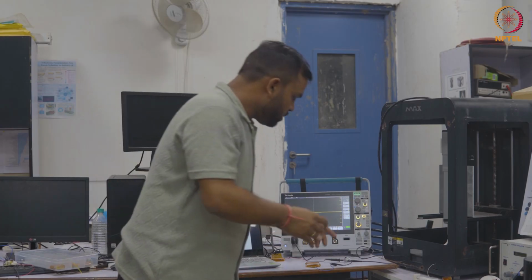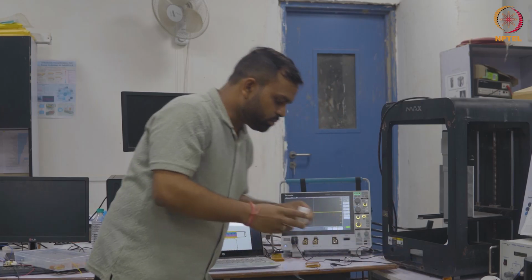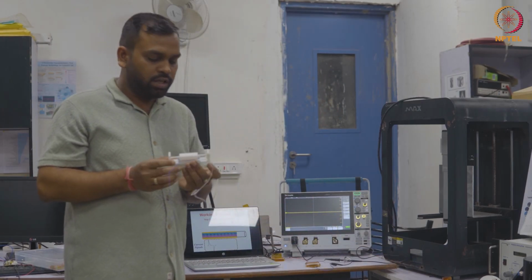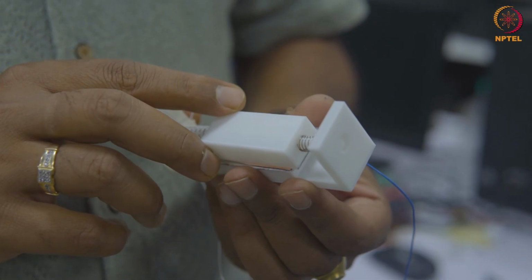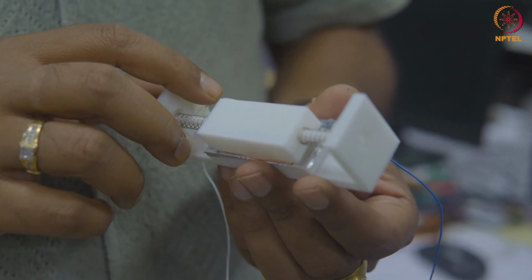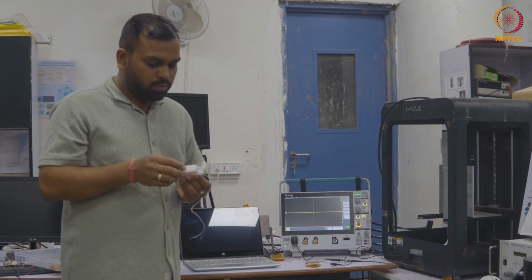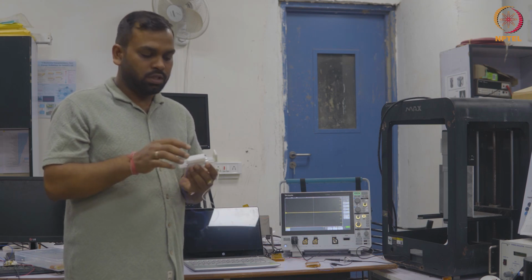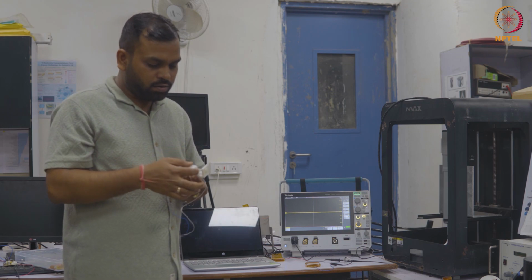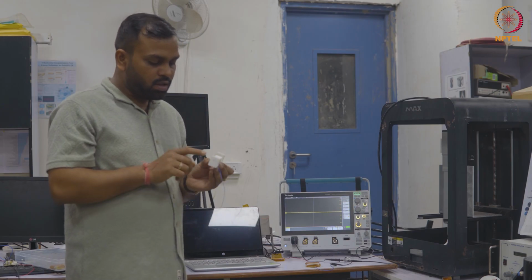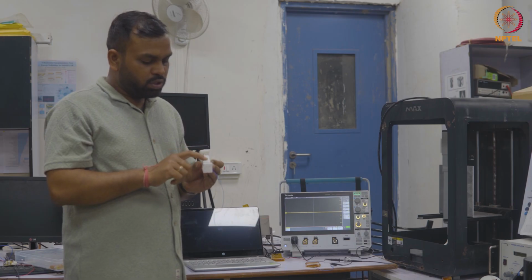So now, apart from contact and separation mode, we have a sliding TNG also. Both surfaces will rub against each other. Again, in this also we have FEP as well as aluminum, and both surfaces will rub against each other. We have applied some spring, so that with continuous vibration, there will be a motion between both the surfaces.